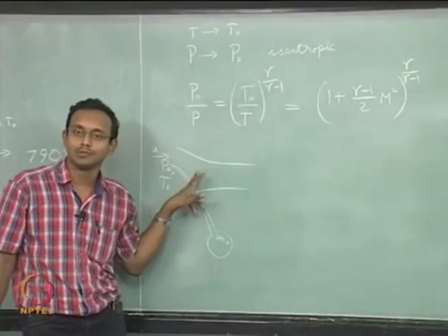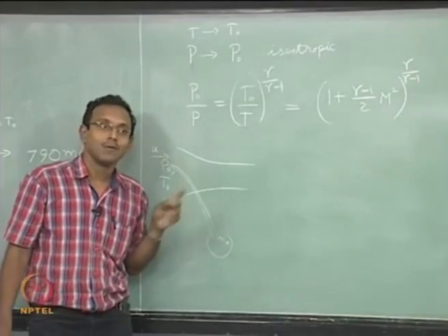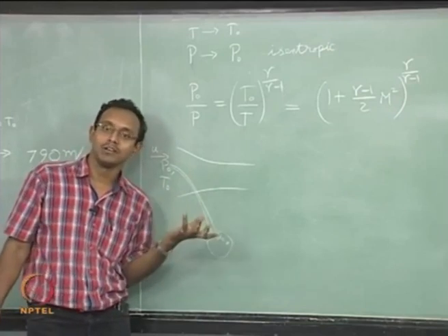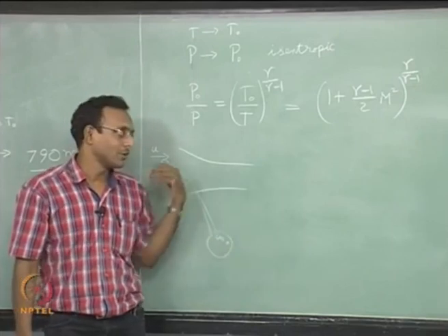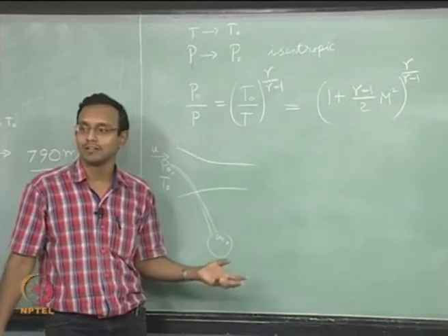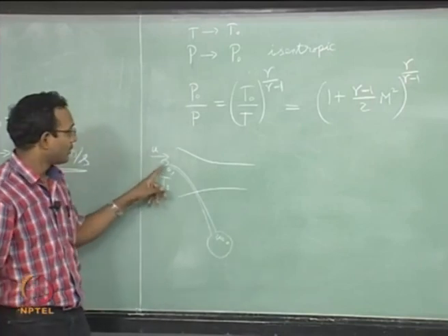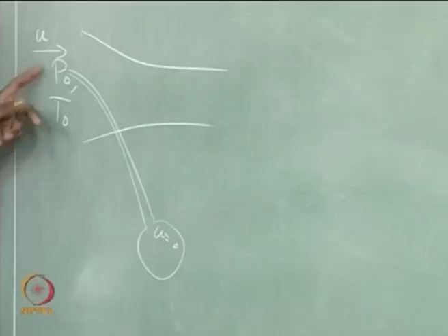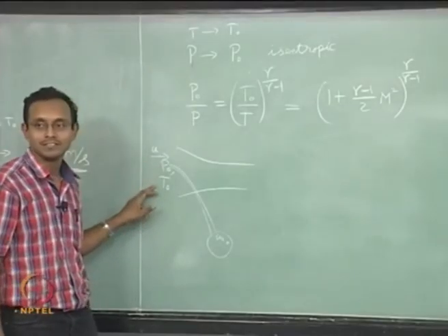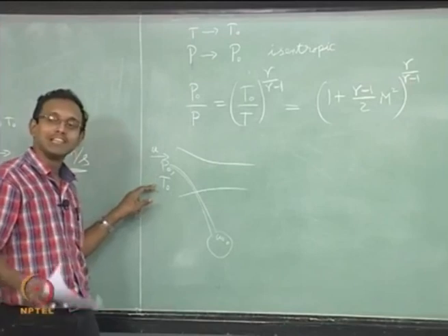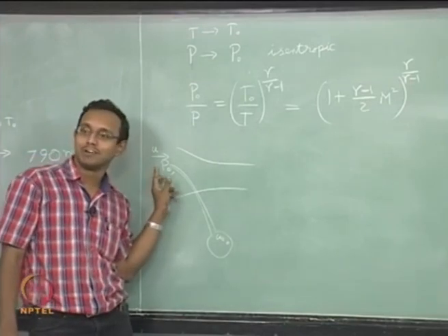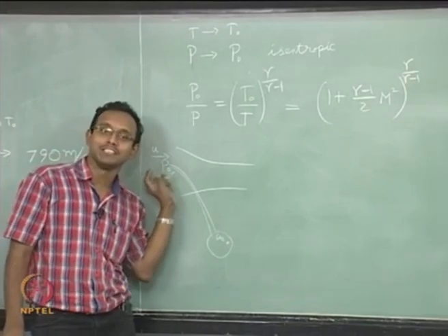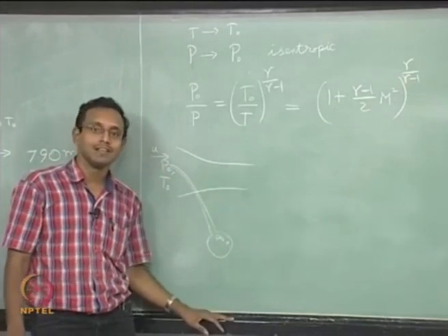Can be done in subsonic flow, supersonic flow, anything. Okay. Only when it goes to Mach angle, Mach cone, those are the things that is defined only for supersonic. Everything else I am talking about here is all for subsonic or supersonic. Okay. So I could define these, and the usefulness of this will be seen when we start solving problems. It is very useful to have something like this. And I will just tell you one peek into the final thing. If I tell you that my flow is isentropic, P naught and T naught do not change all through my flow. Okay. We will see why later.